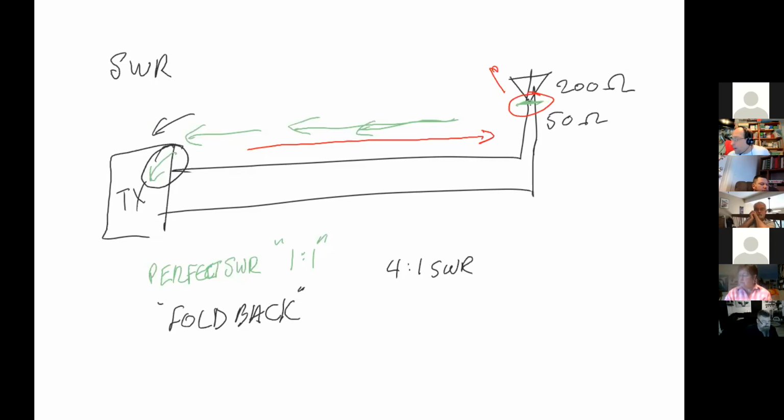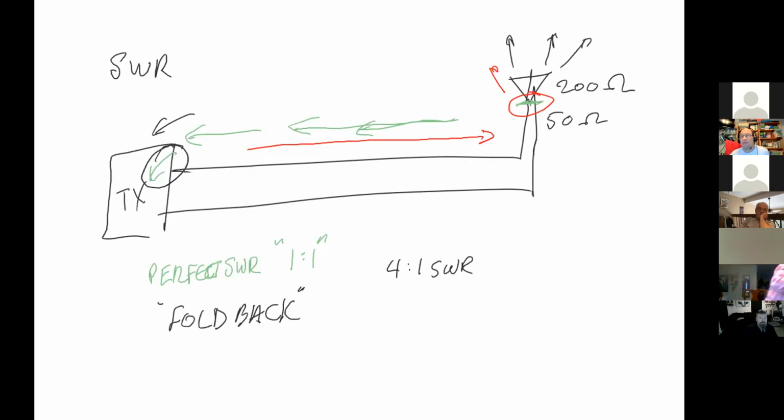Okay, what happens to power that's lost in a feed line? What does it turn into? Heat. Heat, okay. And so why is it important to have low SWR? It'll protect your components. It'll also, how much signal comes out if you have a bad mismatch up here? Much reduced signal. Much reduced signal, that's right.